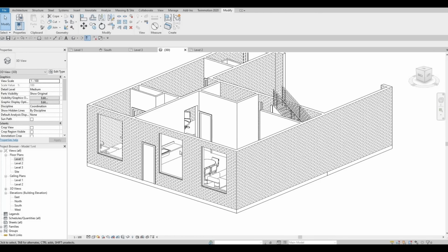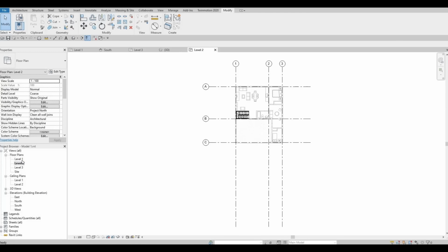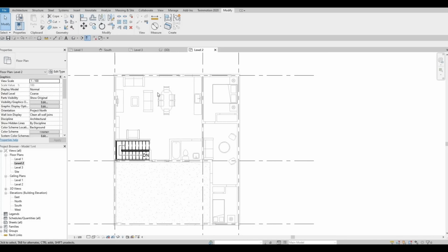So in terms of adding the mullions, we're gonna do that later on. I wanted to finish the second floor first before doing the mullions or the design of the window. So now let's go to level 2 and let's zoom in there. So good thing the overlay for the underlay is base level number 1. So we were able to see what's going on below, especially on the stairs area.